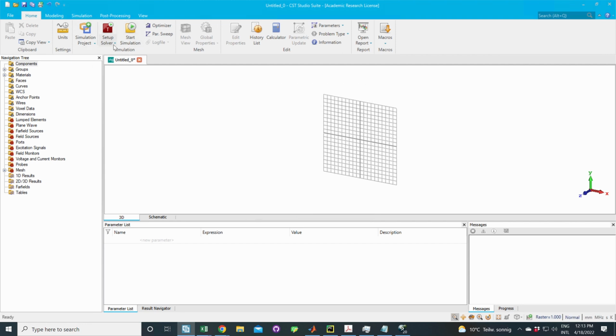And then the next thing you want to do is to change your solver type to the Eigenmode solver. You could see different solvers here: time domain solver, frequency solvers, integral equation. But today we are dealing with the Eigenmode solver because we need some figures of merit in relation to SRF accelerating, that's superconducting radio frequency, accelerating cavities.